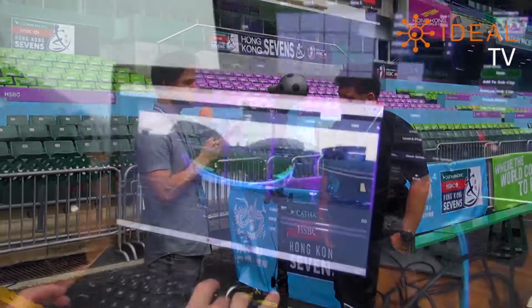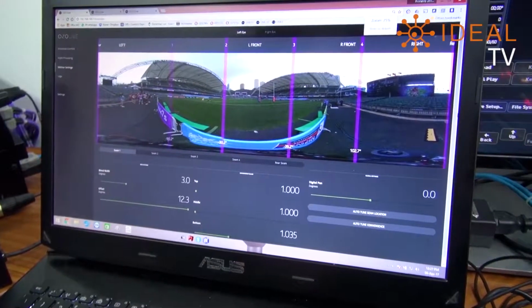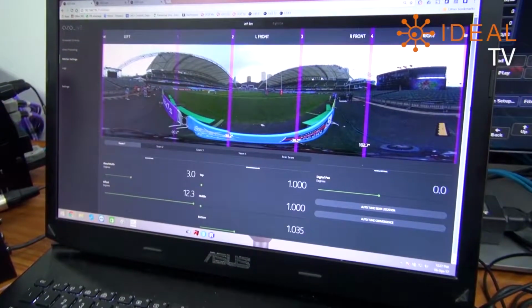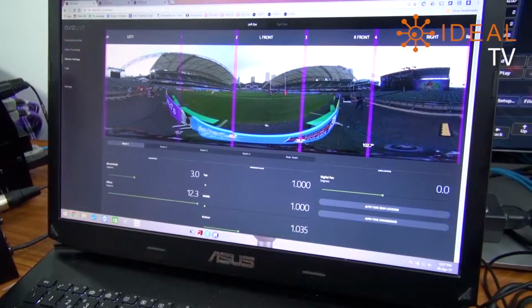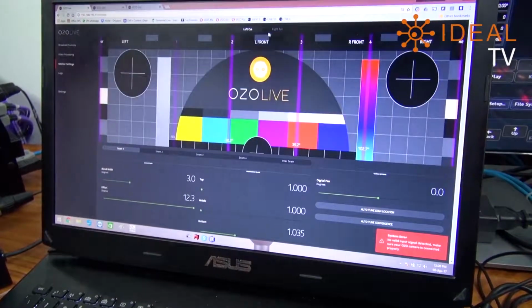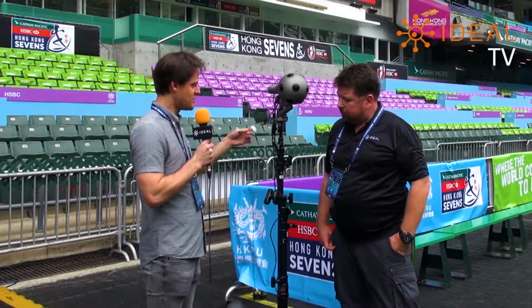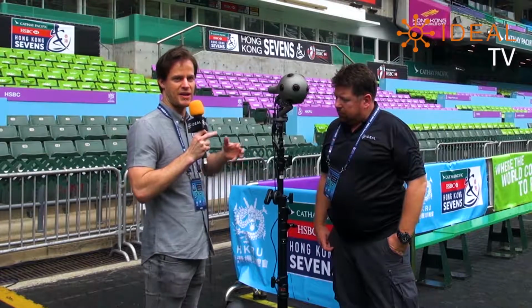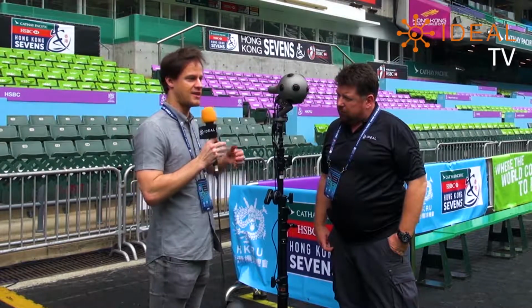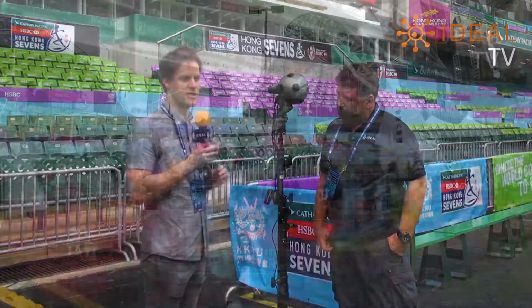It's getting packaged into this fiber line right here and getting decoded on a live stitching server on the other side. So right here, what you mostly see when you connect directly would be just noise because it's raw data. And that's actually the way we are managing to get all this information into this one cable, by keeping the raw Bayer pattern while we are sending it to the stitcher.